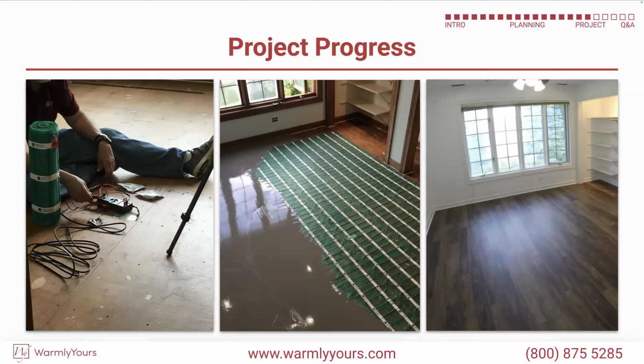And 9 times out of 10 on that bag, it'll tell you a couple things. It'll tell you what primer to use. You have to use primer 99% of the time, and it'll tell you what kind is required. And it'll also tell you how long it takes to cure, because you don't want to turn the heating system on before the cure is complete.